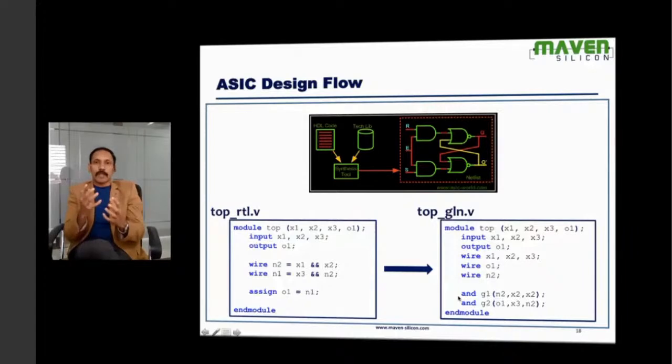We go with positive logic and define the functionality, and we apply SOP and create a NAND based chip. And you can always convert SOP into POS or POS back into SOP. That's mainly for converting NAND based into NOR based or NOR based back into NAND based, right? I explained this in detail as part of the digital module.